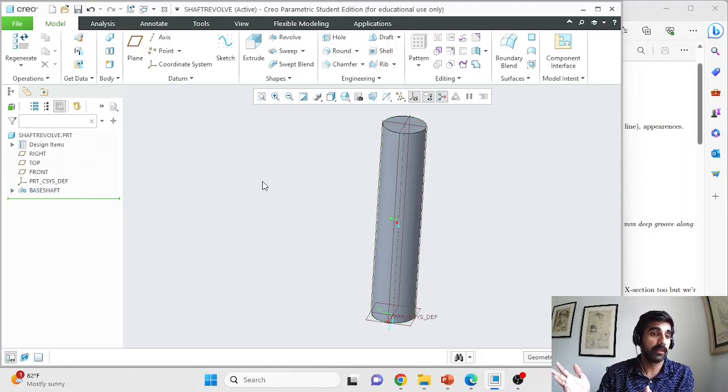So the point over here is that based on what you are wanting to do, you will have multiple options that you can choose from within Creo, and once you have some more practice, you get a feel for which option is better suited for this operation, better in terms of efficiency, where you have to spend less time creating that feature. For cylindrical features, revolve is a pretty good command, but with practice you get a feel for that.